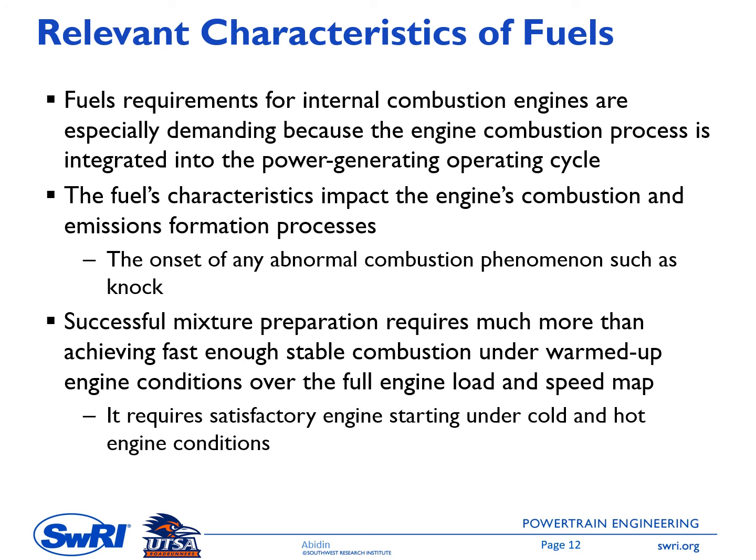It is different from, for example, a steam power system, where the combustion system is separated from the power generating operating cycle. The fuel characteristics impact the engine combustion, which makes sense, and the emission formation processes. The onset of any abnormal combustion phenomena, such as knock, is heavily impacted by the fuel composition and properties. You know, fuel with octane number 87, 90, 91, 96, and so on. These fuel properties have a direct impact on the combustion performance, in this case knock.